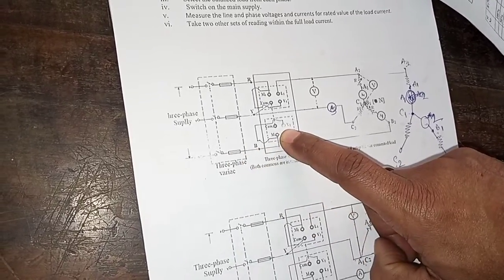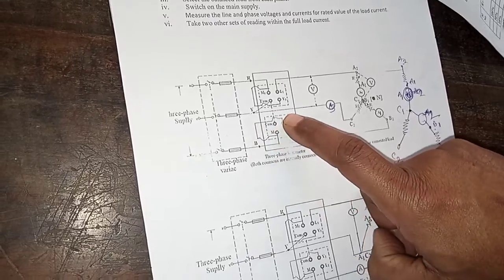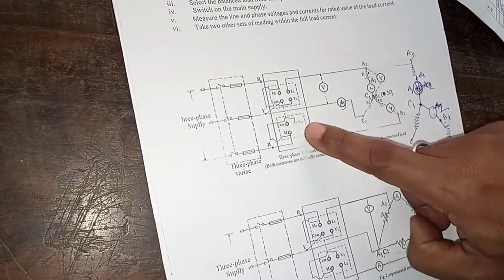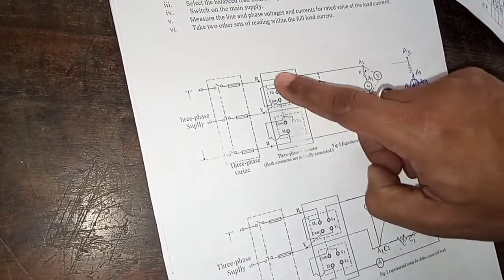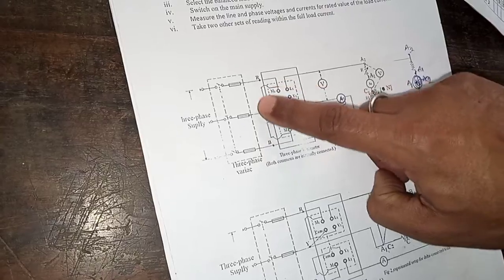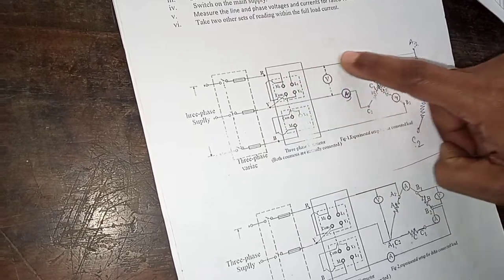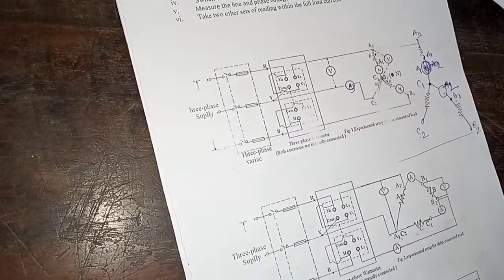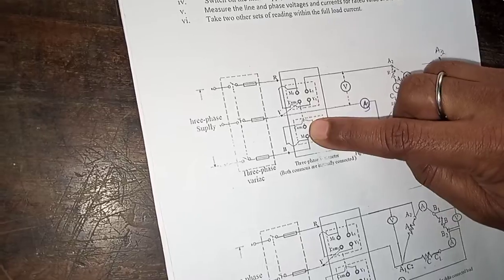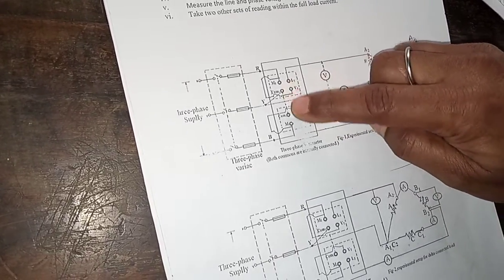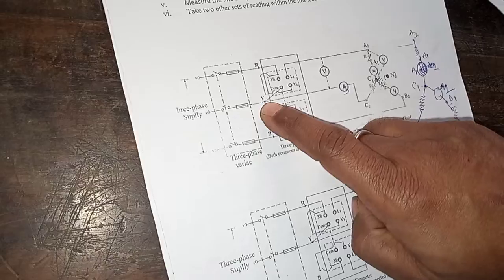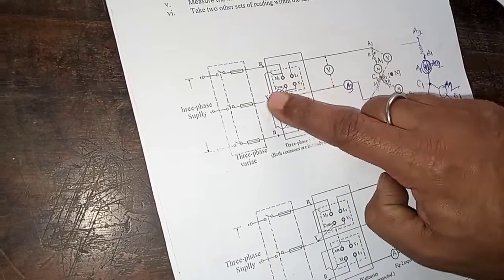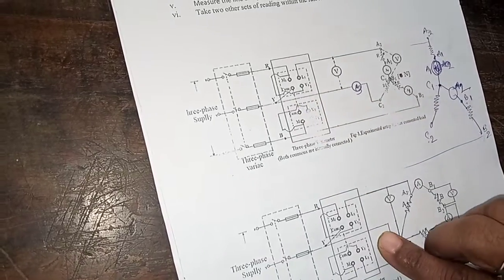You see the supply is coming from the main here. Then M is shorted to V, and from L the current is going to the load. Here also from M it is entering, M and V are shorted, and from L it is going to the load. Both the commons are internally shorted, so during the experiment we do not need to short them. It is internally shorted, but any one of the common terminals should be connected to the Y phase. That means both common terminals are indirectly connected to the Y phase.